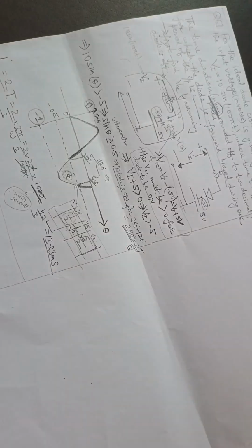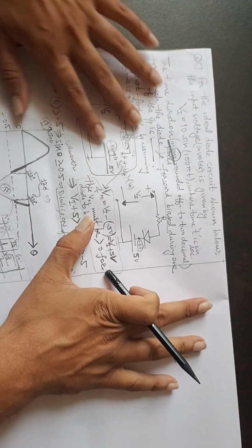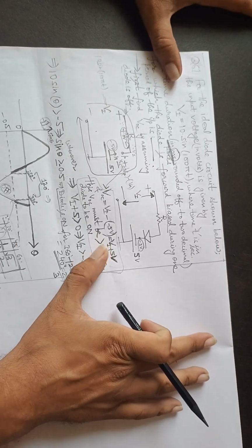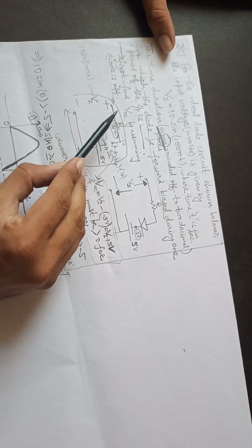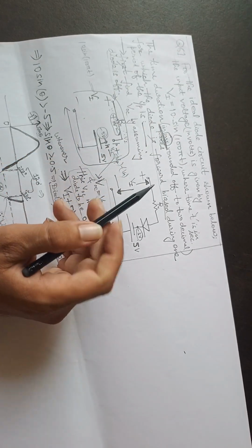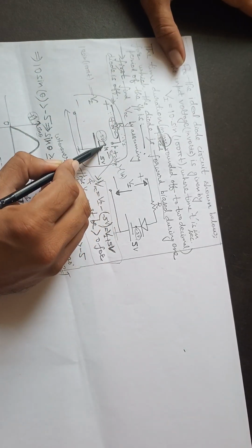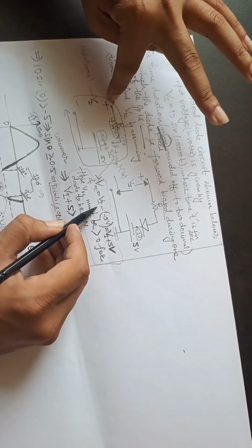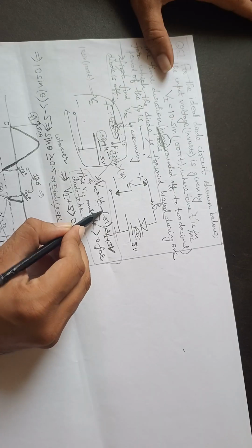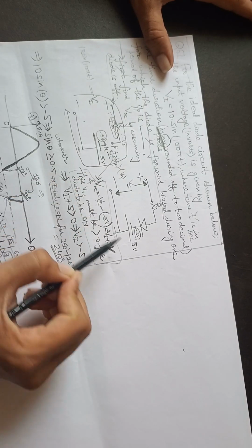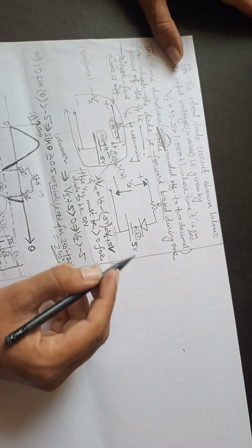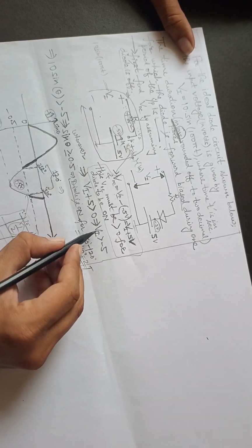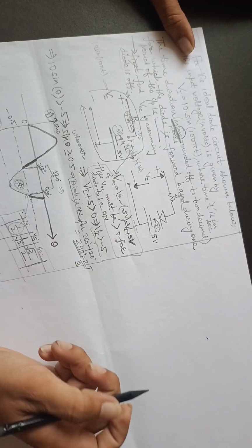First of all, we will find out when the diode is on. Since the voltage is swinging, we will first find the open circuit voltage VOC by assuming the diode is off. So VOC will be VP minus VN. VP is basically VI when the diode is off, and minus this voltage, which is minus 5. So VI plus 5 is VOC, and for the diode to be on, VOC must be greater than 0, which means VI should be greater than minus 5.